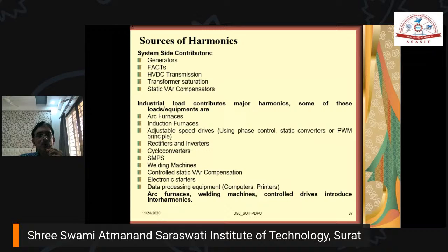So the switch that came, the high power switch, means harmonics. So the SVC is nothing but what? The combination of shunt capacitor and shunt reactor with high voltage and high current thyristor. For what purpose? For very fast and accurate control of reactive power, it is called SVS or SVC.